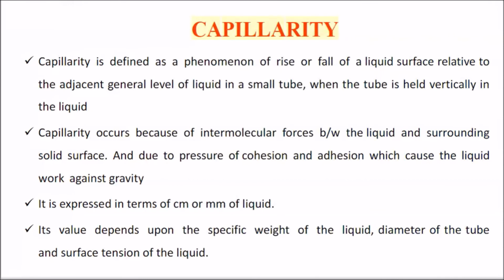Capillarity. Capillarity is defined as a phenomenon of rise or fall of a liquid surface relative to the adjacent general level of liquid in a small tube, when the tube is held vertically in the liquid. Capillarity occurs because of intermolecular forces between the liquid and surrounding solid surface, and due to the presence of cohesion and adhesion which cause the liquid to work against gravity. It is expressed in terms of cm or mm of liquid. Its value depends upon the specific weight of the liquid, diameter of the tube and surface tension of the liquid.